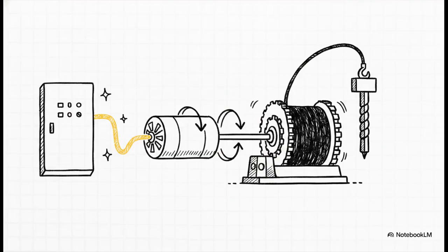And that brings us to the final leg of our single-line journey. That beautifully conditioned variable frequency AC power flows right out of the converter and hits the mechanical application. It drives the motor, which turns the shaft, which spins the drawworks drum, spooling the wire rope, and physically lifting the load on the rig floor. We have literally gone from a drop of diesel to physical, heavy lifting torque.